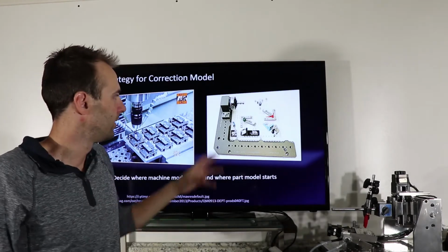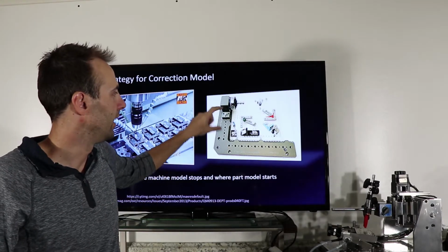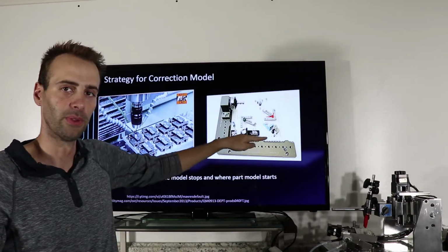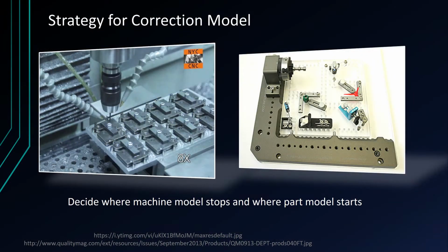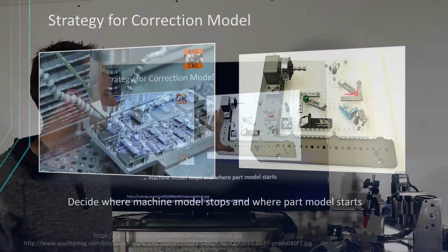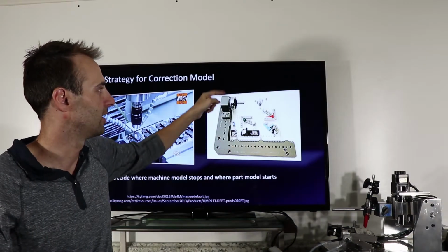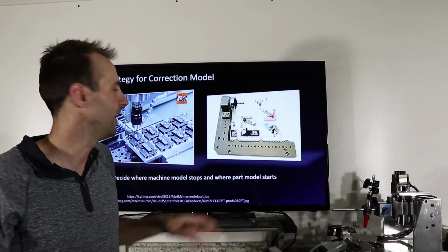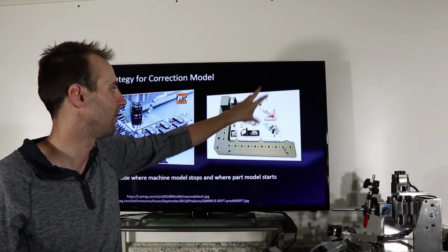So you bolt this thing on and then calibrate to this. Everything that goes in there becomes a part offset or an intermediate to a part, and again, it's repeatable. So we calibrate to this and calibrate our rotary axis and all that, and then we can take our parts in and out.